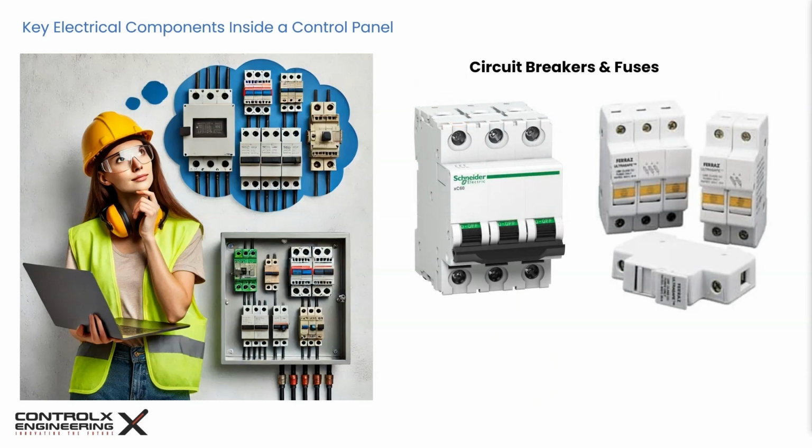Circuit breakers and fuses. These are crucial safety devices in power circuits. Their main role is to protect the circuit and connected equipment by stopping the flow of current in case of overloads or short circuits. Fuses are designed to blow or open when excessive current flows through them, breaking the circuit and preventing damage. Once blown, a fuse has to be replaced. Circuit breakers, on the other hand, are resettable devices that trip to interrupt the flow of current during fault conditions. They can be manually reset after resolving the issue. Both circuit breakers and fuses ensure the safety and longevity of electrical systems by preventing overheating and potential fires.